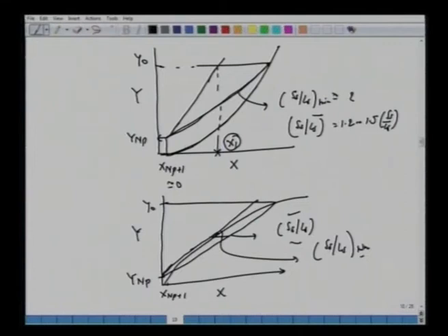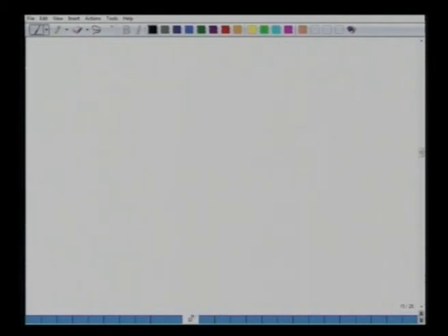This slope will give us the minimum amount of adsorbent required. This is very similar to the case of absorption, when we had different types of solubility curves. Then you get this x1, which will give you the maximum concentration of your spent solid. So whether you have concave downward or concave upward, one has to inspect the curve and see where it makes a tangent. Now we move on and see how we can apply the Freundlich isotherm equations.